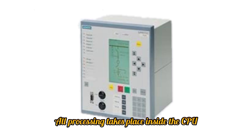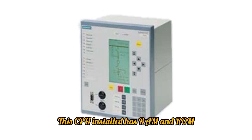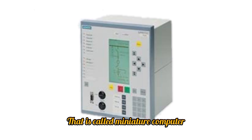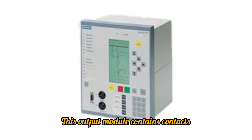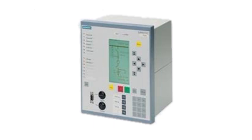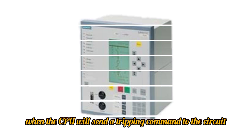All processing takes place inside the CPU. This CPU has RAM and ROM installed, which is why it is called a miniature computer. This relay also has an output module. This output module contains contacts. These contacts are energized when the CPU sends a tripping command to the circuit breaker.